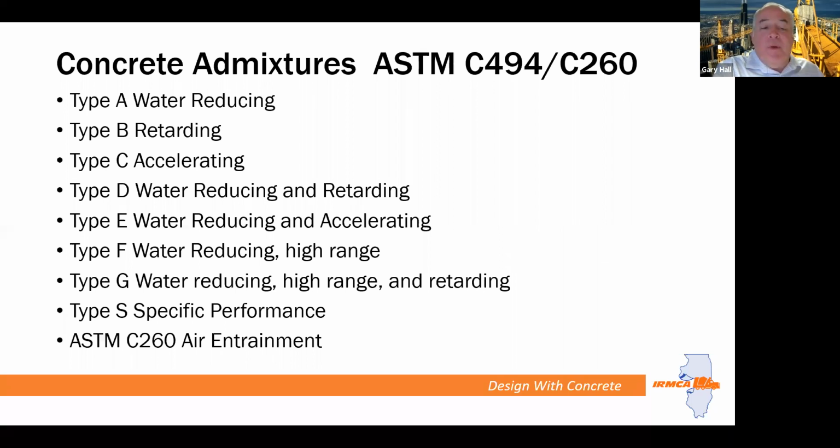Beyond the workhorse, we have what's called type S, or specific performance admixtures that play a real key role in producing high performance concrete under certain conditions with high life cycle expectations, unusual placement conditions, et cetera. And then the C260 air entrainment obviously is the spec that applies to providing an air void system in the concrete for air entrained concrete. Next slide, Scott.